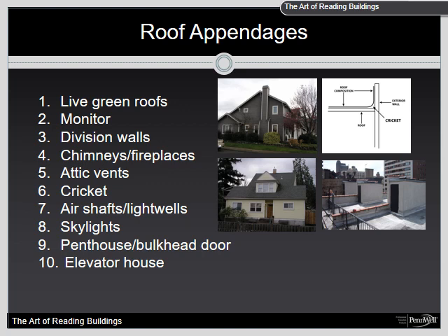Now the problem with these prefab chimneys, as I like to call them, is the creosote built up in the tube, and then once that tube gets rusted out, then you have all kind of fire spread into the chimney area where it's just that void space between that metal piping used for venting of the gases and the wood construction that surrounds it. The masonry fireplaces are definitely a bit more durable.